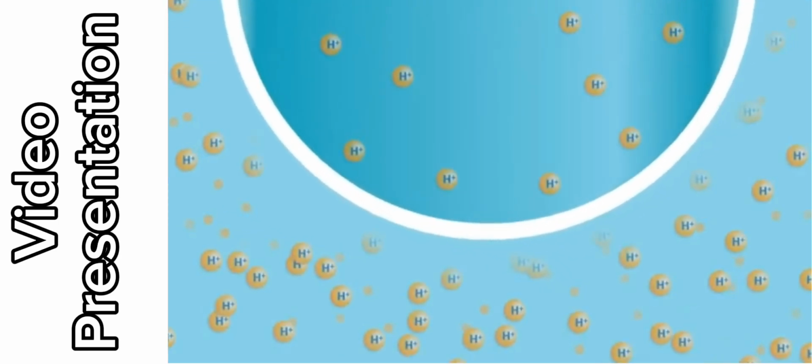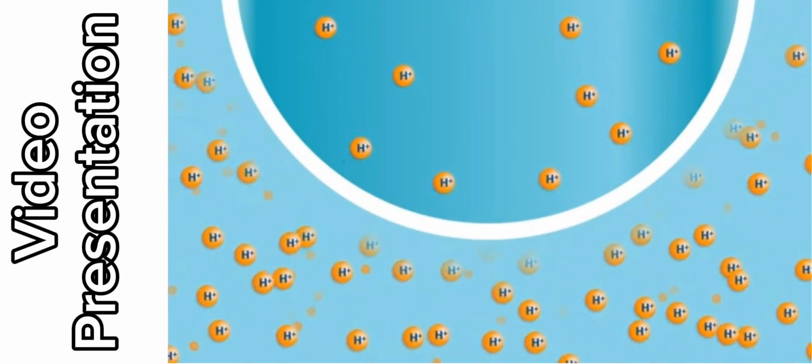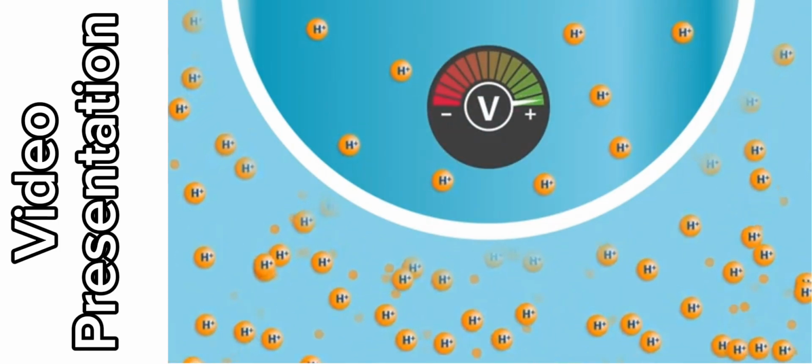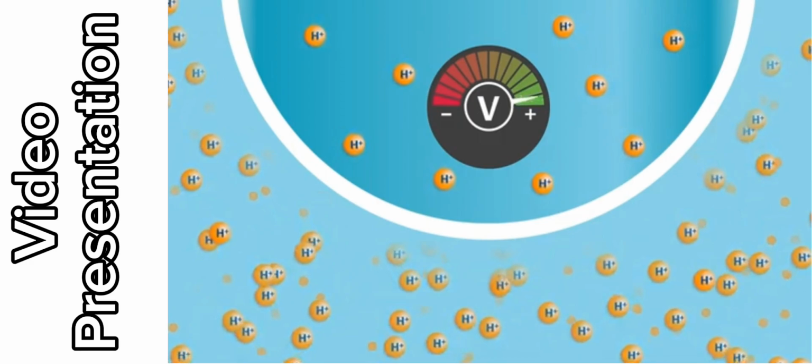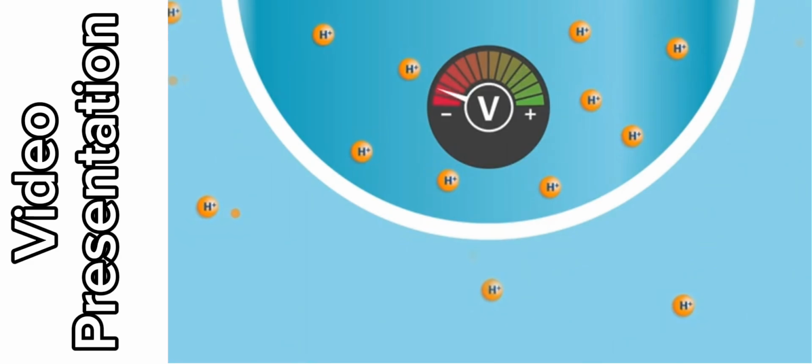If the hydrogen ion concentration is higher on the outside of the glass bulb than on the inside, a positive voltage occurs, indicating the process is acidic. If the hydrogen ion concentration is lower on the outside of the glass than on the inside, a negative voltage occurs, indicating the process is basic.